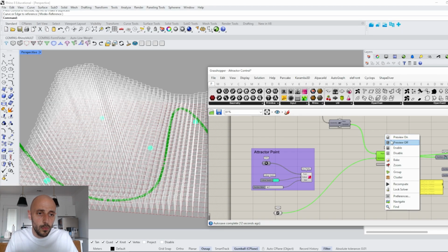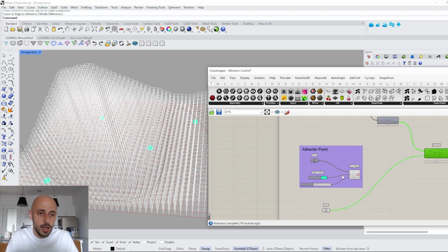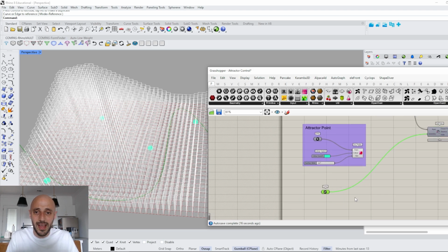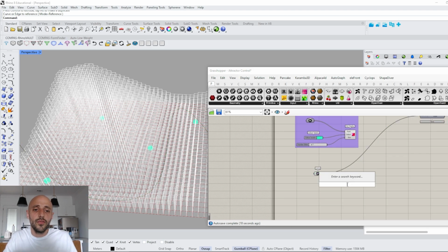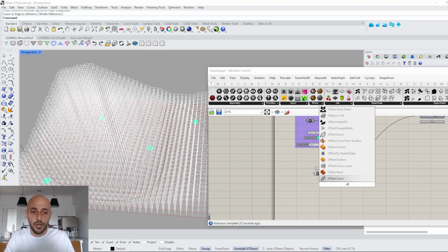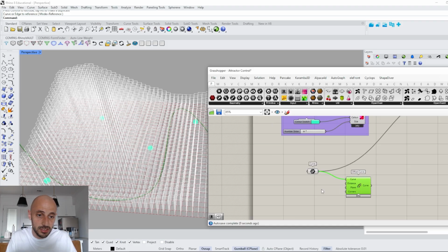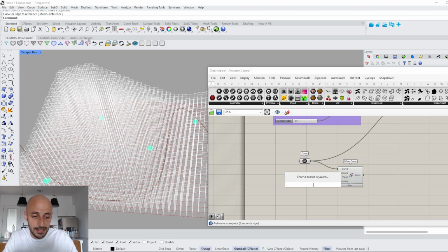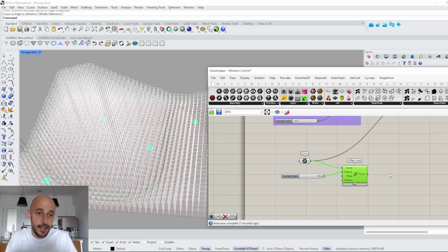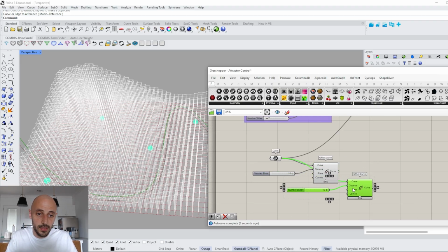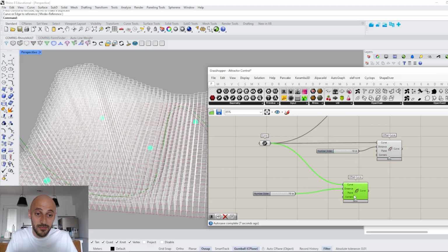So one thing to avoid here: maybe we say, okay, I want to use this curve as a road. If you follow the very first tutorial that I have, we were offsetting these curves, right? So I can offset this curve in two different directions. Let's say this is going to be 10 meters, and this is going to be 10 meters. And I can do the same thing with the same curve, but this time with -1, and I can put this in.